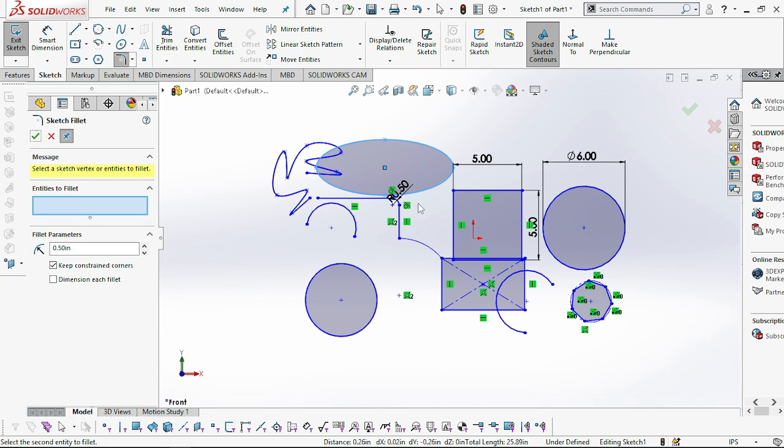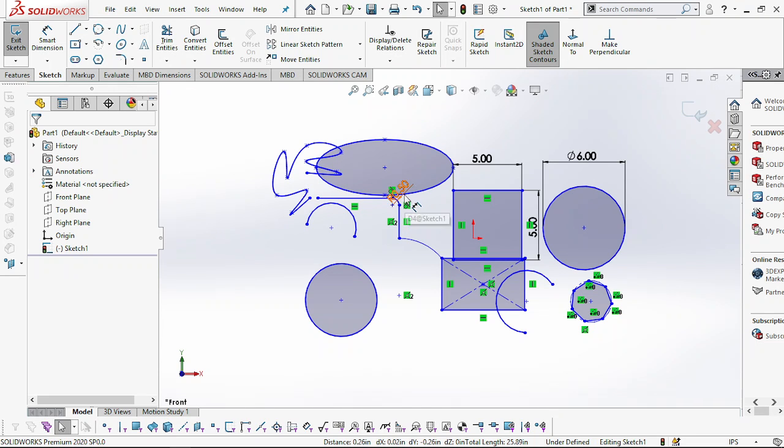Okay, and then if you come and zoom your work to view it clearly, you are going to see that after there you click OK, and if you come in your work, you are going to see that now the corner which was too sharp is no longer sharp. That's all about the fillet. You can observe it clearly under your work. The corner which was sharp is no longer sharp. Now it means that the fillet is used to prevent sharp corners when we are designing.